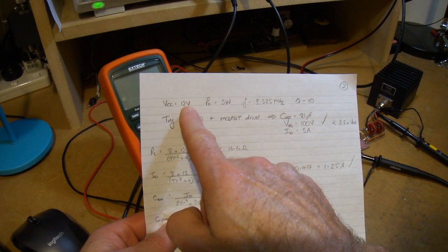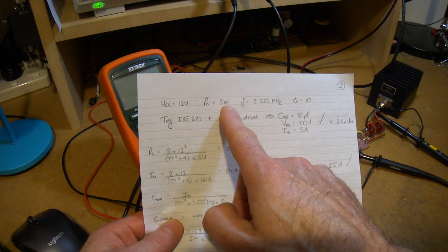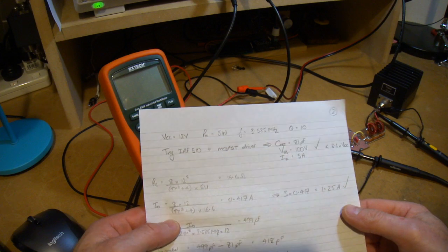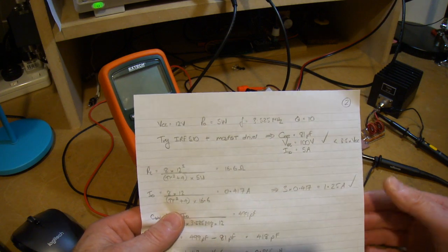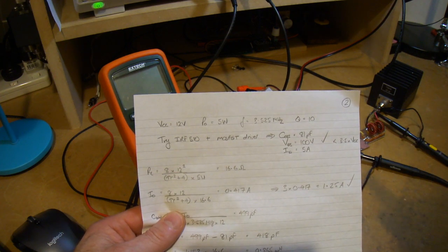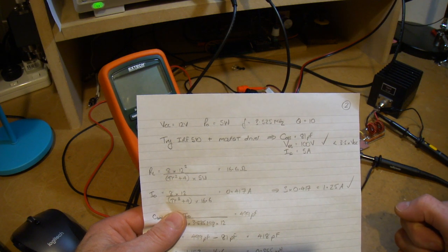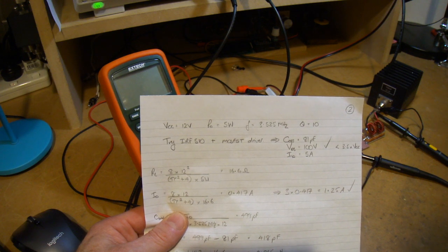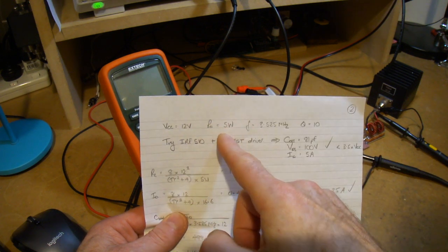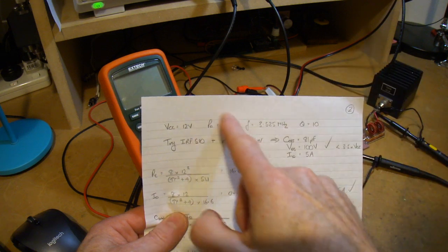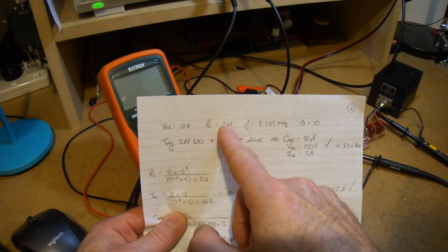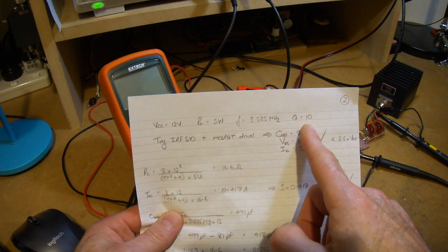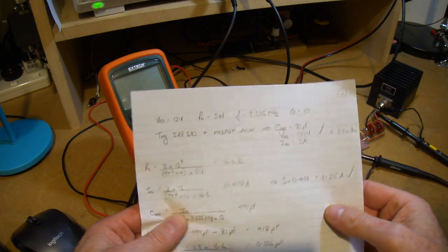I used VCC at 12 volts. I decided to go with a power out of 5 watts. I note others have mentioned in various derivations and examples that in their experience they aim for even 150% of what they wanted, because that's what actually would turn out. Right or wrong, I've just run with a power out of 5 watts. Frequency of oscillation, as I mentioned, 3.5 to 5 megahertz, and I've used a Q of 10.